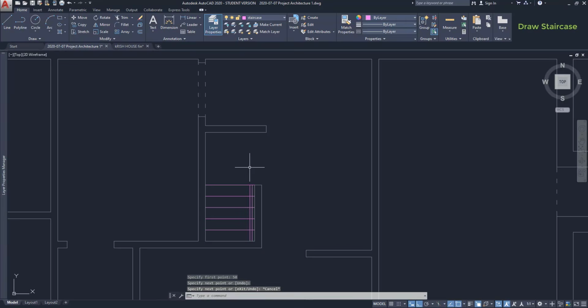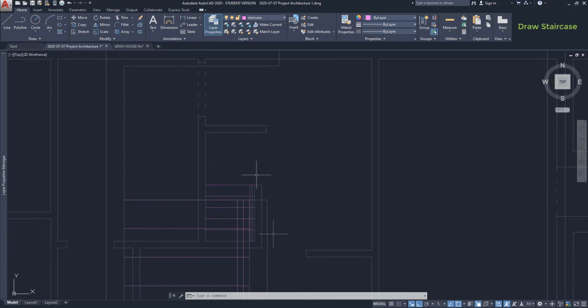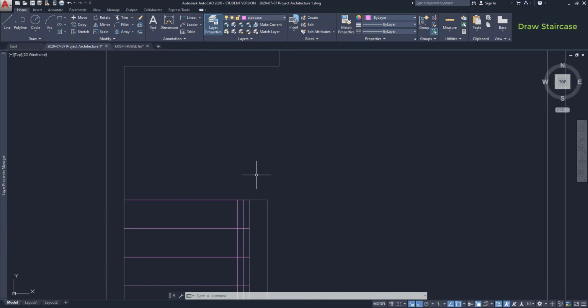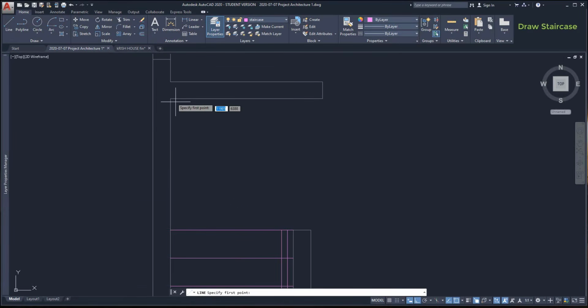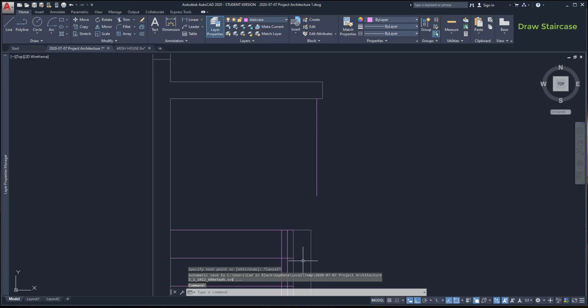Then the last riser. It's a bit more complicated, but I will show you one of the several ways to do it. I'm going to start with the vertical line, which is where the staircase starts. It's located at 1250 mm from the wall, and the length of the line is a bit shorter, just 870 mm. And that is the run width of the first riser.